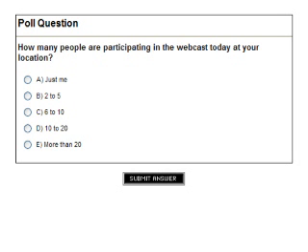I don't know what the questioner's facility looks like, but you can disinfect flows without removal of the solids, but you're going to put in a lot more chlorine. And when you put in a lot more chlorine, of course, there are more issues dealing with disinfection byproducts because you'll have more precursors in there, and you're going to put in higher doses, so you're going to create that many more disinfection byproducts. So those are the things you have to consider in doing this. In Columbus, there is no downstream water intake, so it's not as big of an issue in terms of the disinfection of the raw CSOs, so to speak.